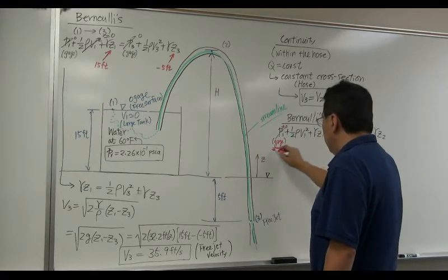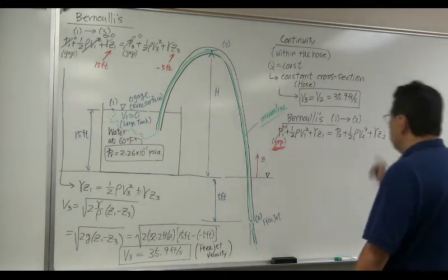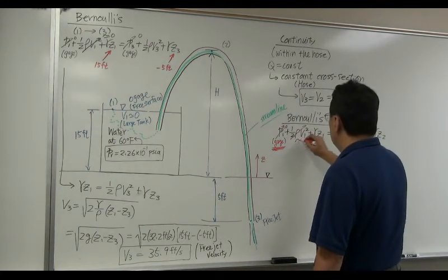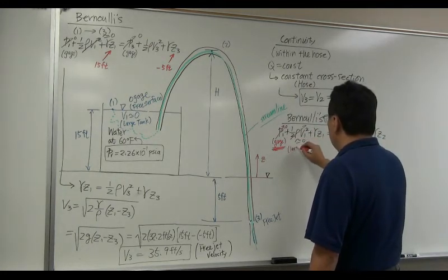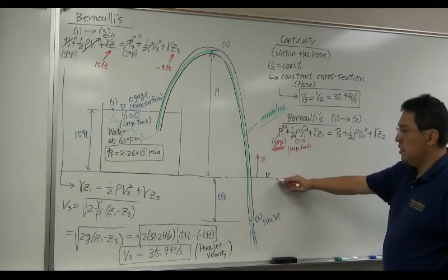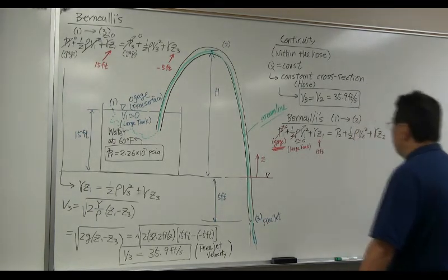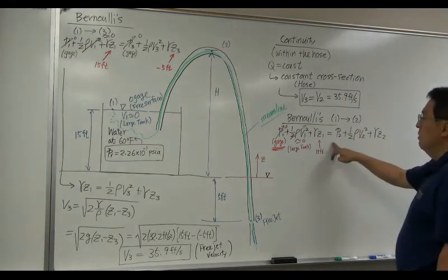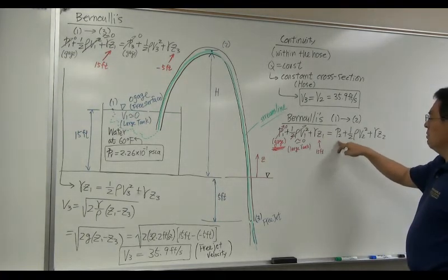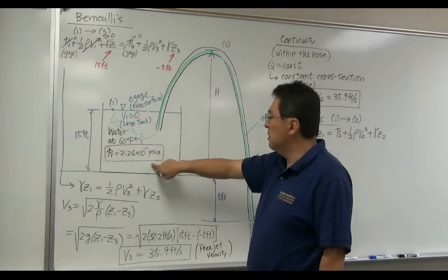I'm going to underline gauge, emphasizing, hey, I'm talking about 0, but this is 0 gauge. B1, approximately 0. Large tank. Z1, measured from here, 15 feet. P2. Okay, well, the condition of P2 is, suppose P2 becomes this value, that's where the cavitation begins.